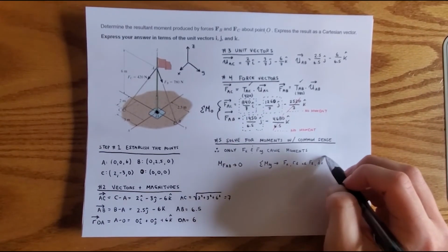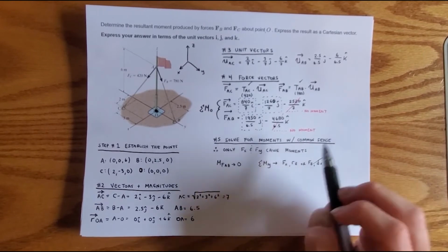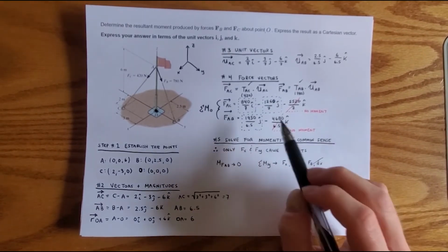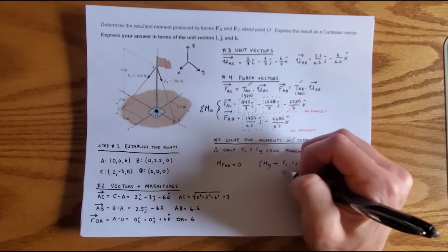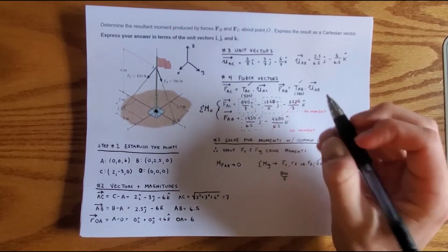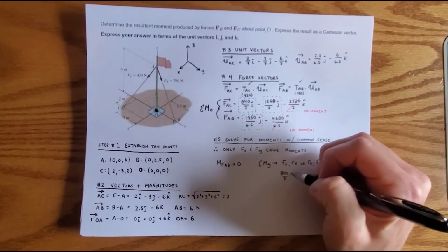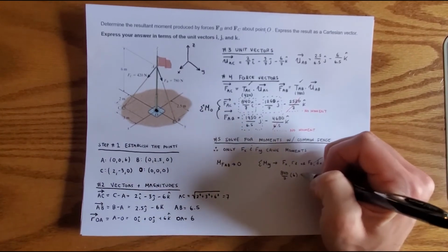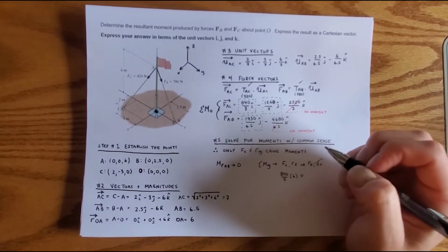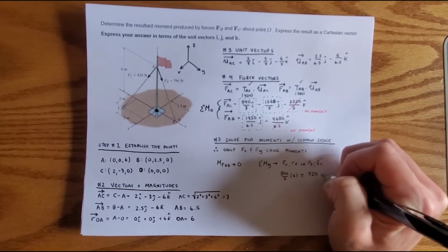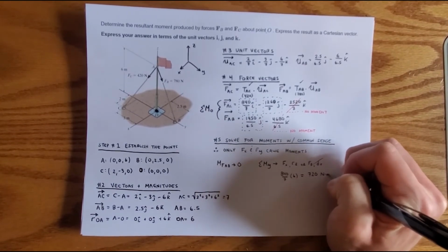Now this case doesn't exist in our particular problem, but we do have an x force and we do have a z moment arm. So the x force in our particular problem is 840 over 7 times the distance in the z direction, which is 6. And if you look at the answer to this, the moments about the y are going to be 720 newton meters about the j.